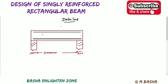Then the cross section, and we already found out the spacing of the stirrups. I am mentioning stirrups with a blue mark. So the stirrups will be like this. From this edge to this edge, like this up to the end, with the same spacing only.